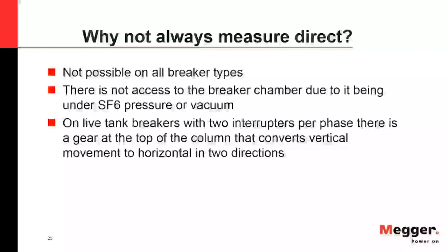So for any critical SF6 breakers, high fault, especially generator circuit breakers where they're always breaking a lot of current, you're going to want to perform this dynamic resistance measurement. But it's an addition to your time and travel measurement, where you hook up a little bit of a current injection box and test with that.